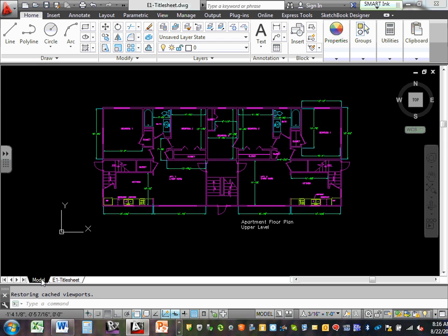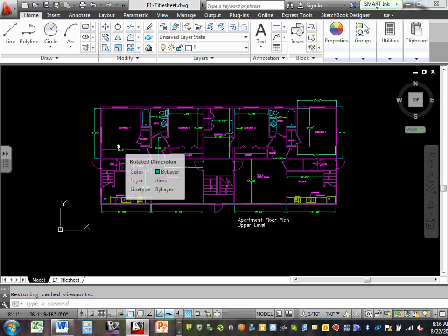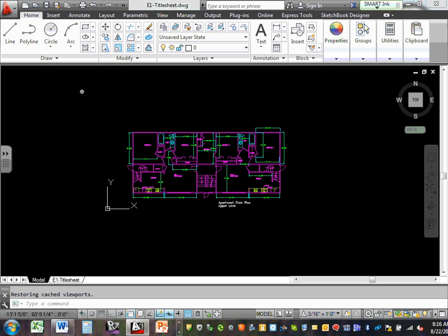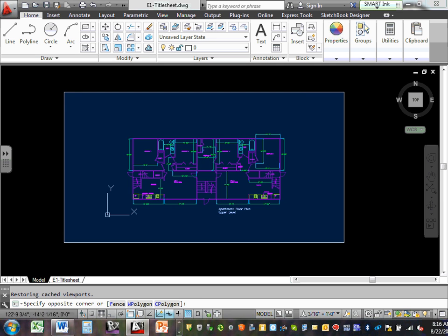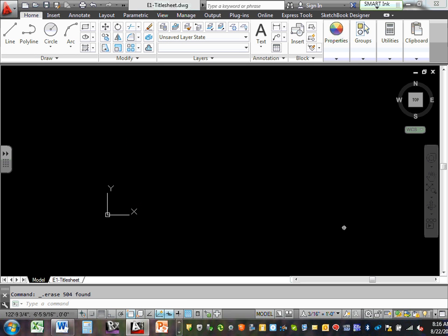At this point, I'm going to do a couple of things. Number one, the E1, guys. E1 is title box. Does not have background. I don't care about this. So do me a favor, go in the model space from left to right and box it in. Select all of it, and hit the word delete. You know why I did the delete? Because I really care less about this setup here. After you delete, hit Z enter, E enter, make sure that everything is clear. You have a clean system to work with.